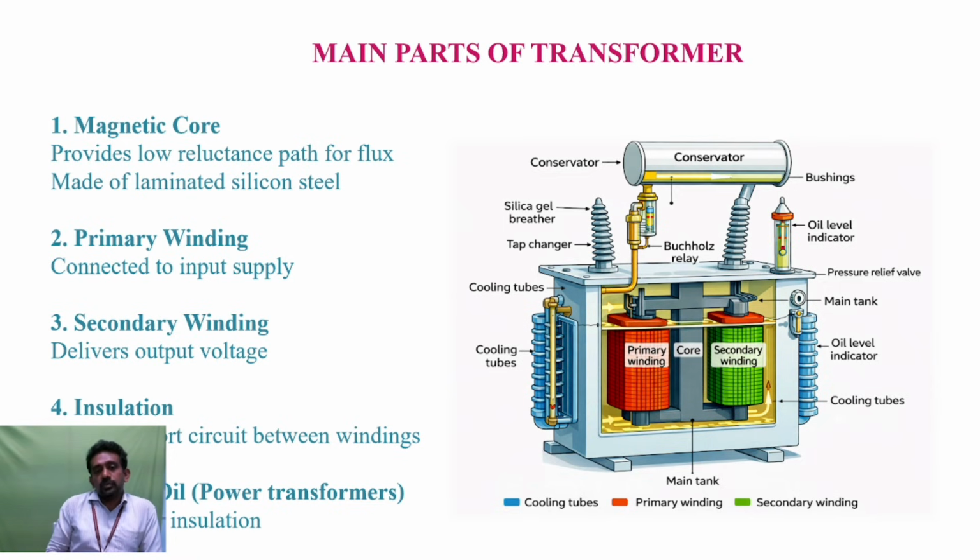And insulation. Insulation is one of the main working parts of high voltage transformers. In low voltage, the air circulation and the air environment surrounding the transformer itself is enough to cool the transformer. But while working in high tension and high voltage applications, a defined insulation part plays an important role, and it occupies nearly 50% of the cost of the transformer.